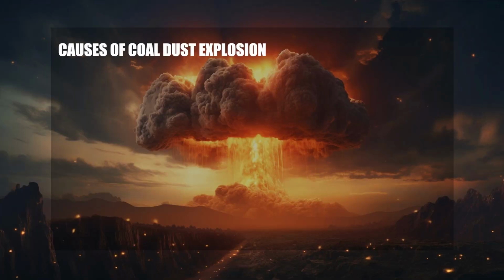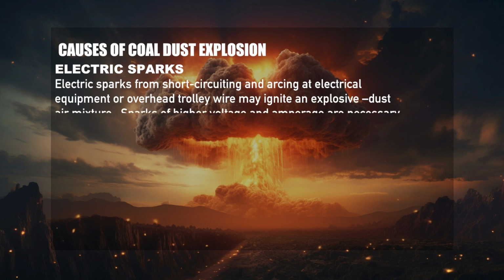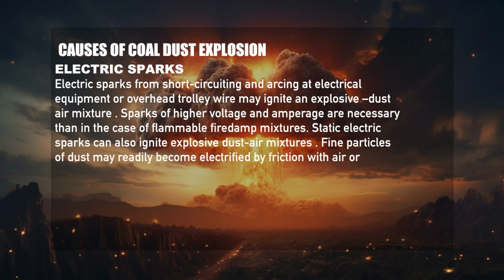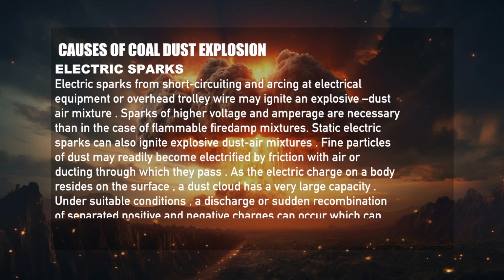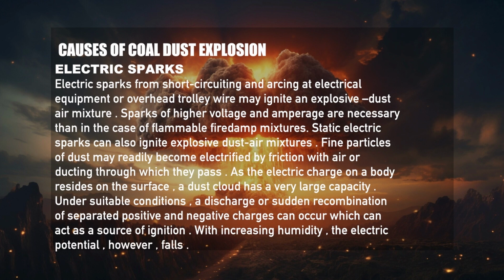Electric sparks. Electric sparks from short circuiting and arcing of electrical equipment or overheated trolley wires may ignite an explosive dust air mixture. Sparks of higher voltage and amperage are necessary than in the case of a flammable fire damp mixture.